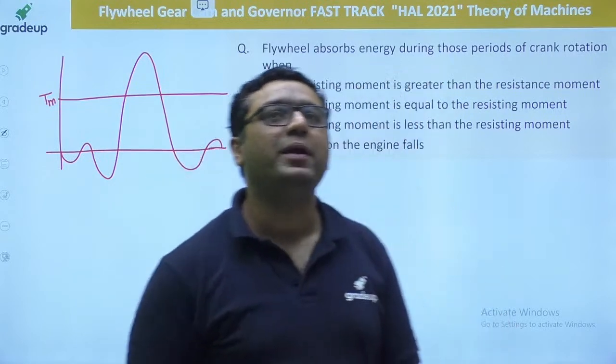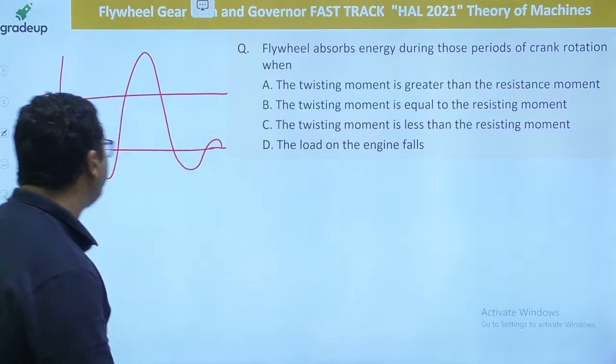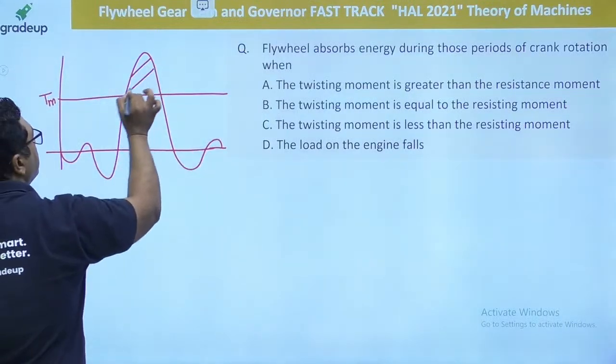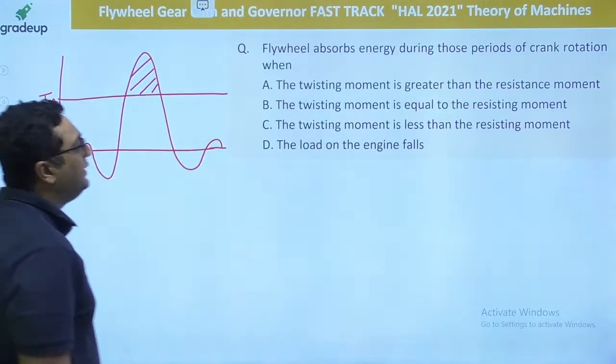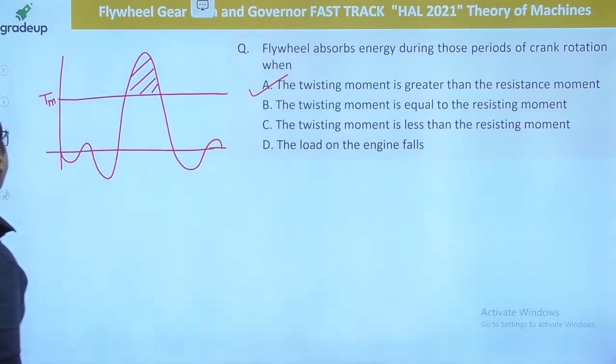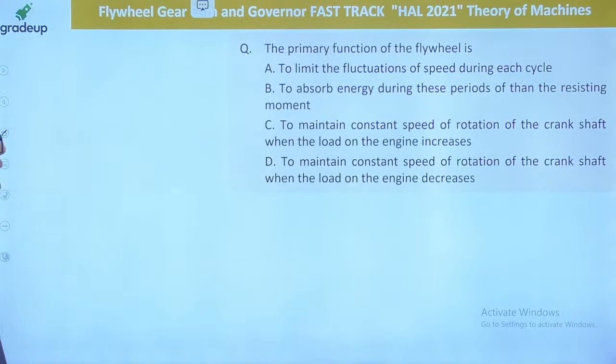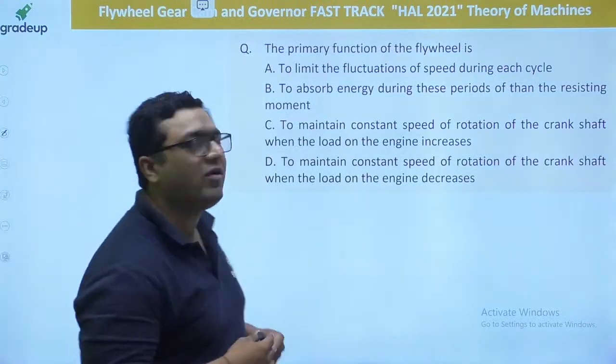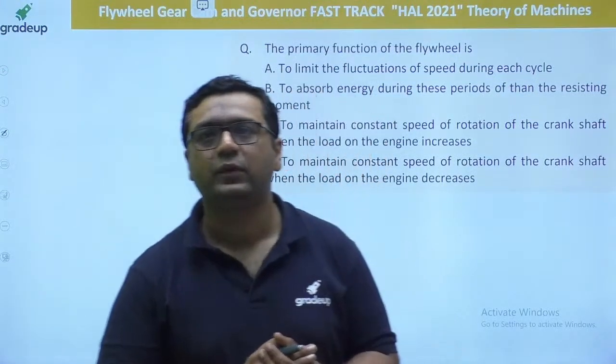Yes, when the twisting moment is greater than the resisting moment. Obviously, in this time the energy will be absorbed. So when the twisting moment is greater than the resisting moment. Very good, guys. Next question. The primary function of the flywheel is?